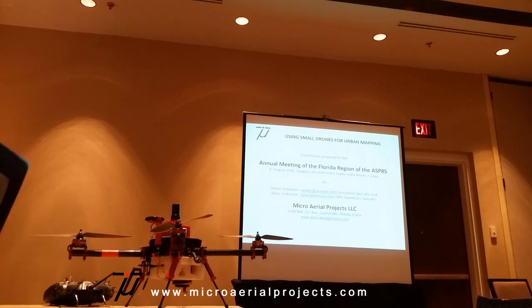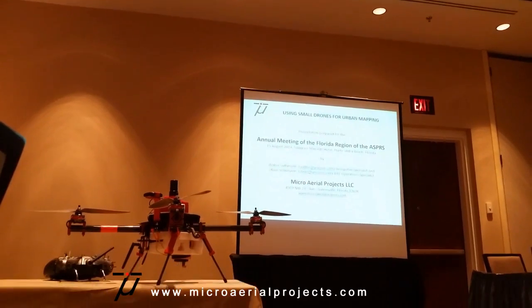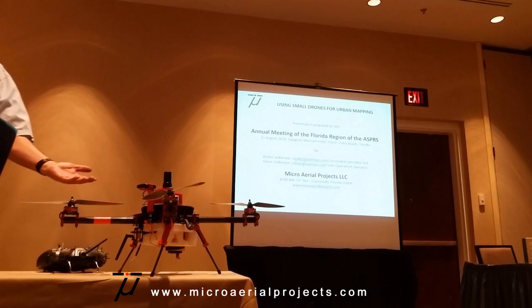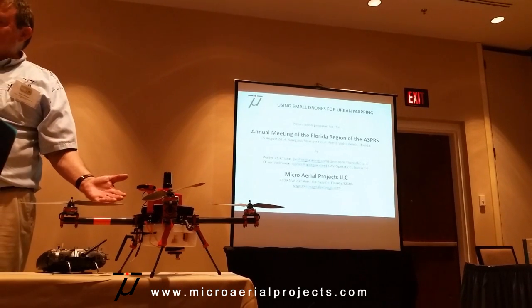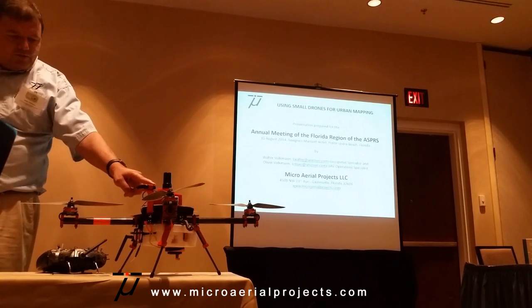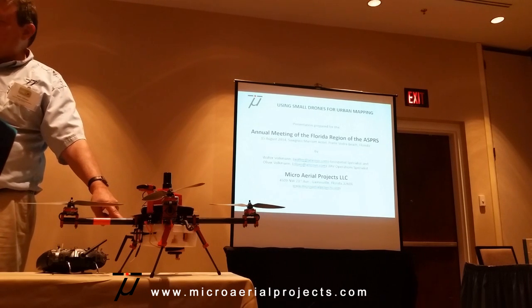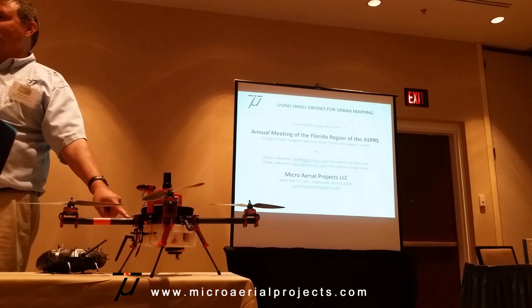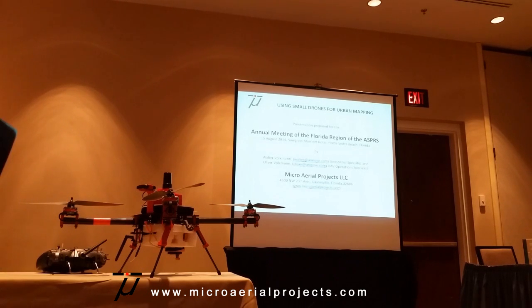So this is actually supposed to be in the toolbox of surveyors, not of photogrammetrists, per se. It's a pretty small GPS. But of course, you have to have some budget for error propagation here. You have the antenna phase center, and then you have the optical center of the camera. That's actually the position that you need to determine.